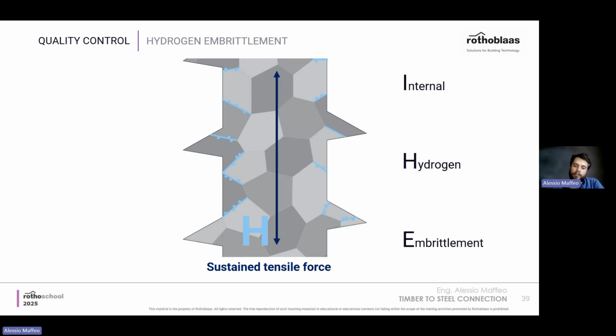Hydrogen, usually the internal, again, is the one that has been englobated in the structure of the fastener, along the grains of steel, and then a small crack could open on the body of the screw, and if there is tension, the screw will crack on that point and then open up.